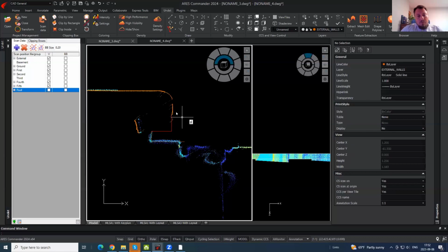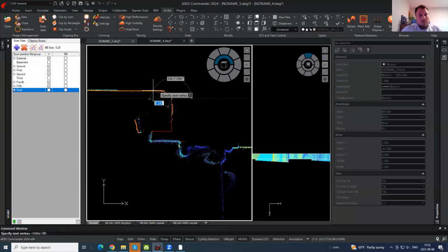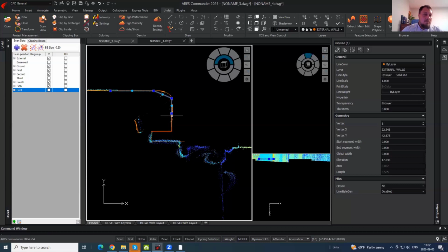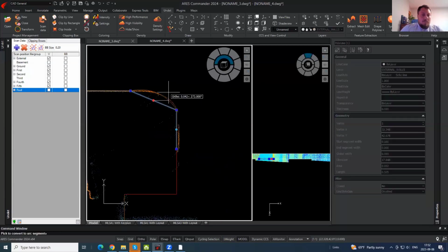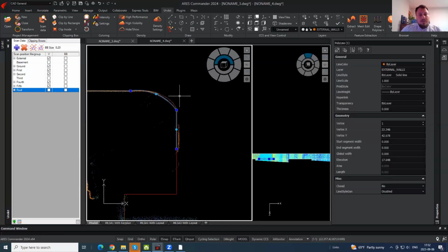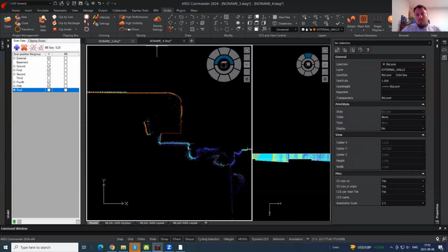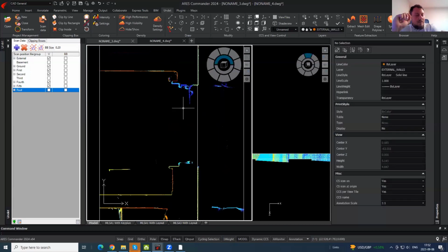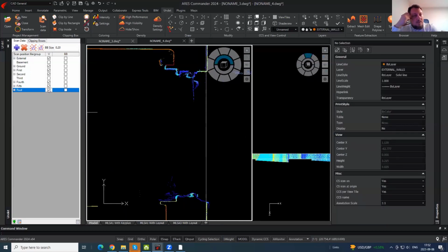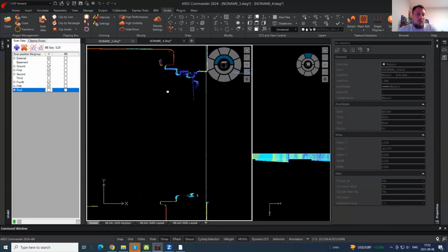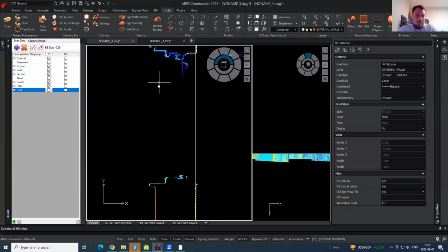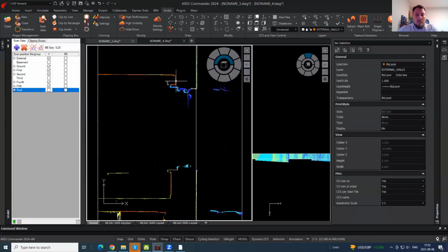But if you have a possibility to use laser scanning and drone together, you can easily import the point cloud files from the drone and laser scanner into the same point cloud project all together, manage visibility and activate. I was told that drone data is rough, so it's not looking as nice compared to laser scanner data. But when you need to receive such information, you can always use the photogrammetry point clouds to have these slices.